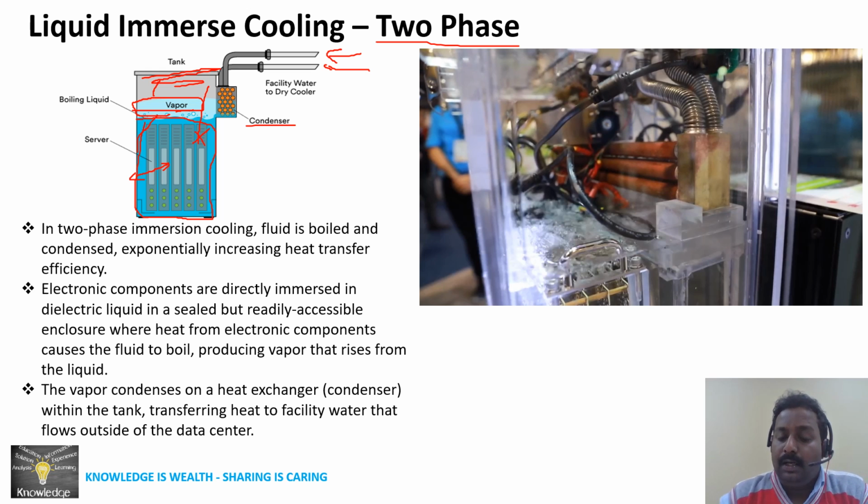So again, it is the best energy optimized solution for data center and the lab area, where heat will directly transfer to the liquid, not the air. We are not cooling in the usual traditional way. PAC is a traditional method where air is used as a media to cool the racks. Here, the engineered fluid is used as a media to cool the server racks. And most importantly, it is directly cooling the hotspot of the lab. So no comfort cooling is required in that lab area, and it is most energy efficient compared to any other method.